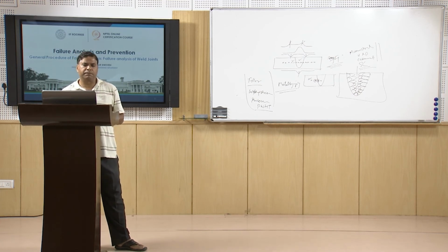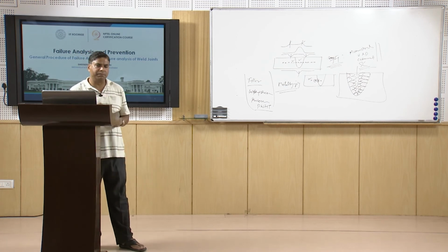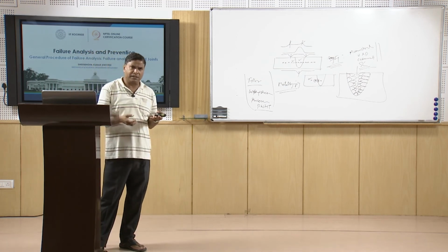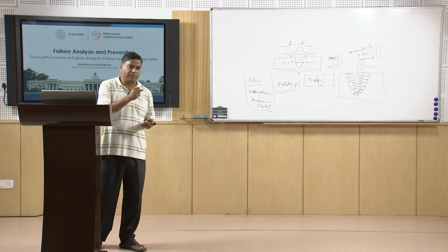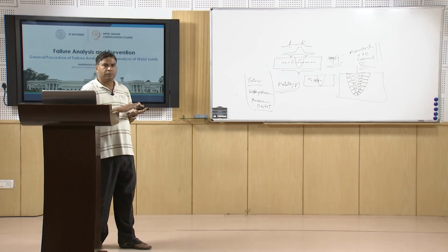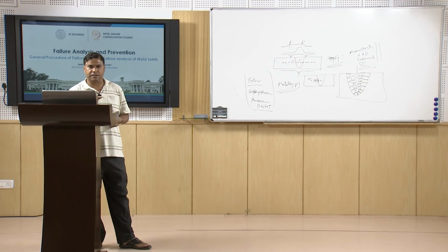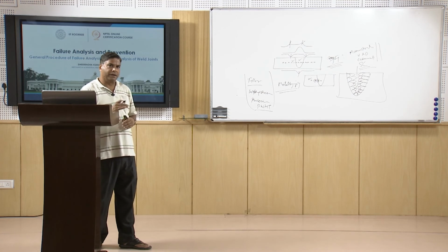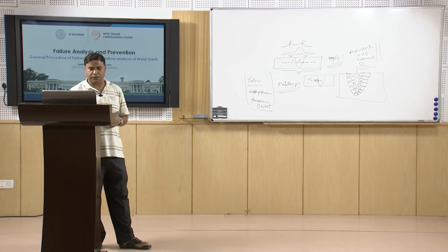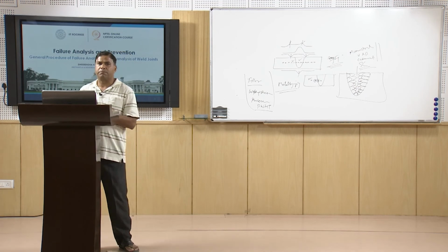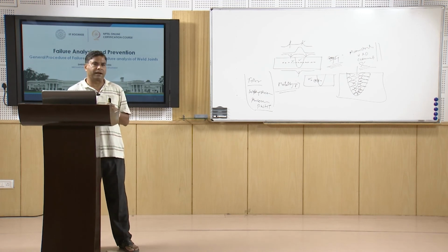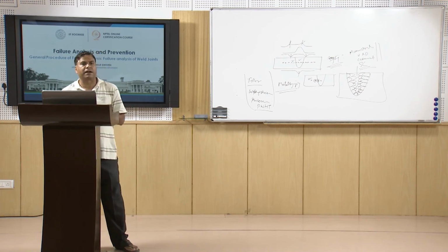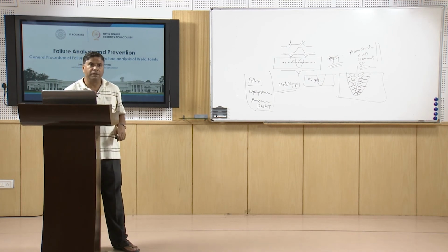Similarly, magnetic particle test is also to be avoided, especially in medium and high carbon steels where electromagnets are used, and for electromagnetism high current is supplied, and when current is passed through the workpiece through the prods, it generates heat at the contact areas from where current is being fed, and that in turn leads to the formation of hard spots. Such hard spots subsequently can promote cracking. So, this can also be a misleading situation, whether the cracking has been there due to the NDT or cracks were present before the failure.